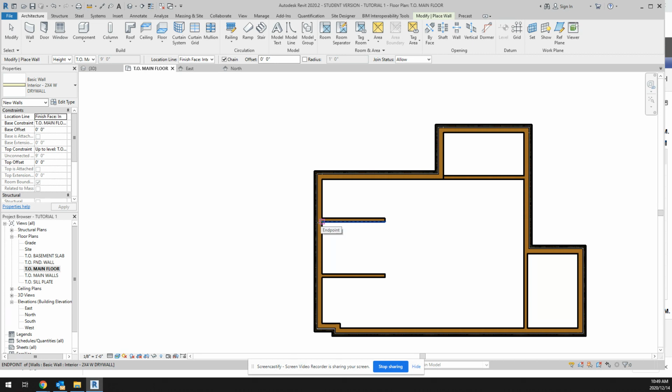So add that to your 10 feet. Then you may have 12 feet, so add 12 feet. And then you have your 4.5 inches, so add your 4.5 inches. And then add whatever the remainder of that space is supposed to be. That'll tell you how long the interior needs to be as I draw this straight exterior wall.